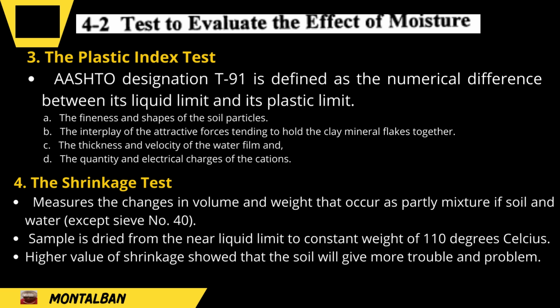For coarse grain soil or fine grain soil with few particles of clay of colloidal size, a small increase of water above the plastic limit will cause particle separation, destroying the attractive forces that provide shearing strength. It simply means that the difference between the plastic limit and the liquid limit is small, so that the plasticity index is also small.